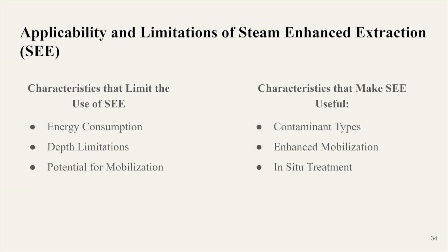To finish the applicability and limitation section, we will go over characteristics of steam enhanced extraction, or SEE. Characteristics that limit the use of the method involve energy consumption. SEE requires significant energy inputs for steam generation, particularly for larger and deeper contamination zones, leading to a high operational cost. Depth limitations as well.